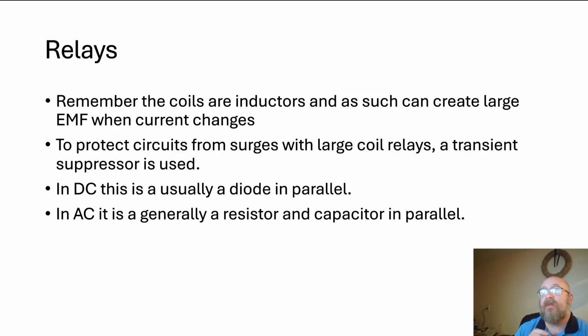Quite often when we're dealing with these, they're actually built into the module itself. We're really talking about large coils, so things that are being used for large solenoids, large contactors, things like that. They generally put the transient suppressor in those modules. So it's kind of unseen, but it's important to know that it does exist in there, and that it's taking the EMF worries off of our mind on those things. But if all you're looking at is a straight up coil and that coil is large, you need to be aware that can create some problems when we try to vary the current through it.